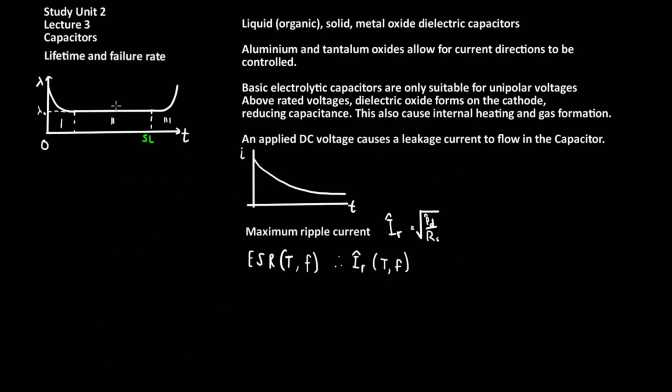The service life of a capacitor is characterized by how long various parameters of the capacitor will remain within some specification. When one of these parameters falls out of spec, then the capacitor is said to be degrading. There are various parameters of the capacitor that can degrade, such as the capacitance itself, the leakage current, the dissipation factor of the capacitor, and so on. Manufacturers will specify what are healthy parameters for the capacitor to stay within spec, and this way the designer can choose the applicable capacitor for a certain application.